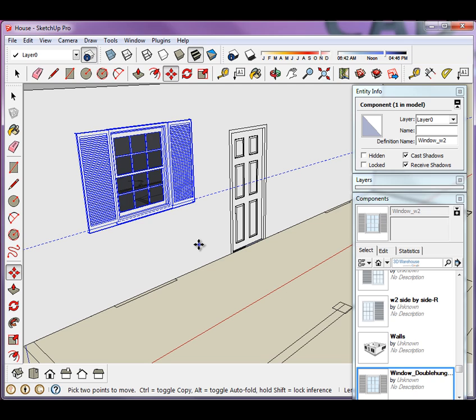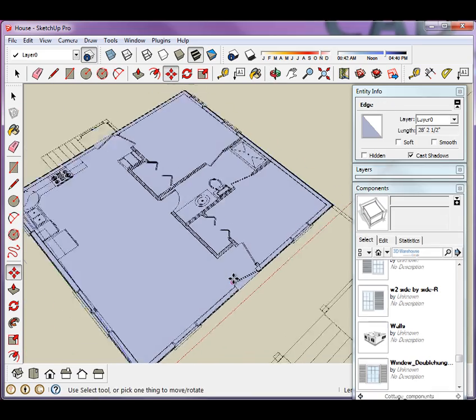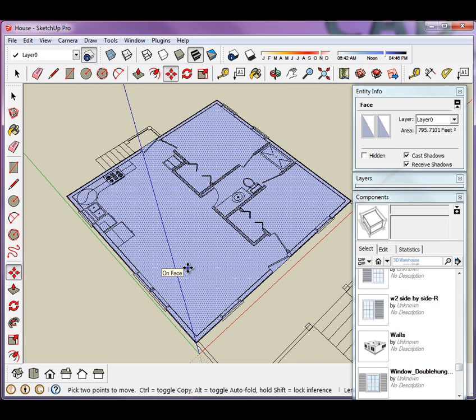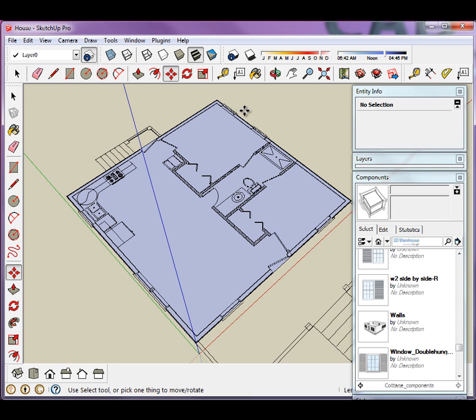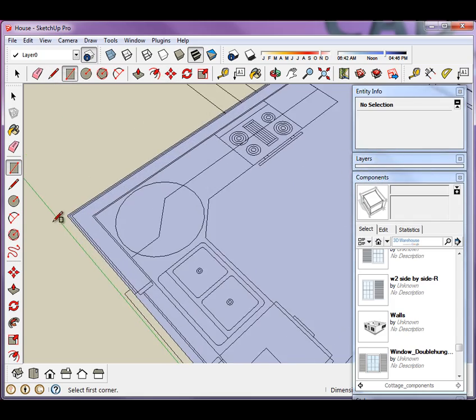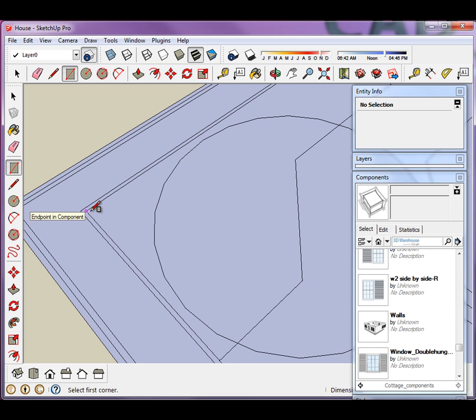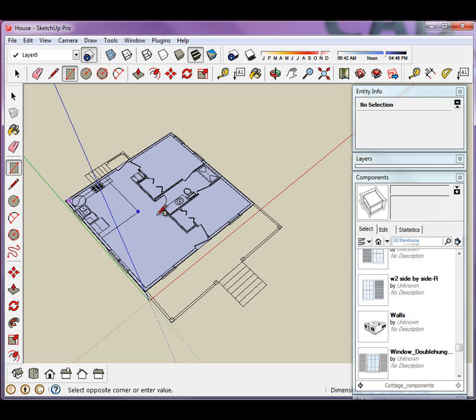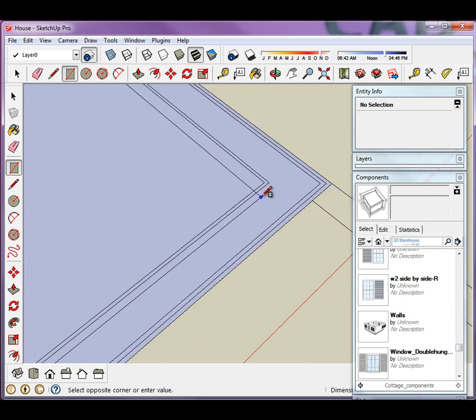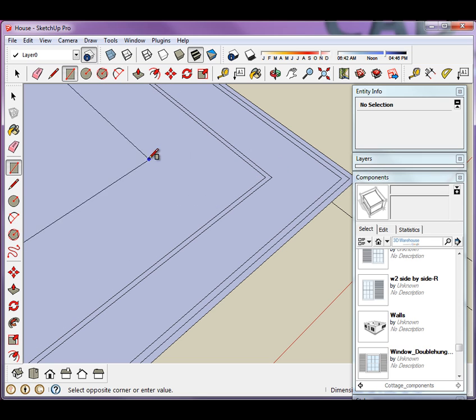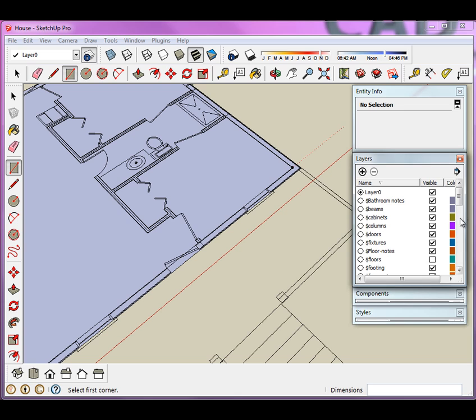However, for this series of videos, we're going to take a look at both the interior and exterior model. So, if we were going to do that, let me undo all of this. Not only would you be tracing the outer edges, but again, you'd have to separate interior and exterior walls, right? So the next thing I would do here would be to draw the boundary of the inside finish of the exterior wall, right? So from here, and again you might use pencil if your wall jogs or changes direction and is not square or rectangular, but this one is, so I could come all the way out here to the opposite side, and then when I turn off my XREF layer,